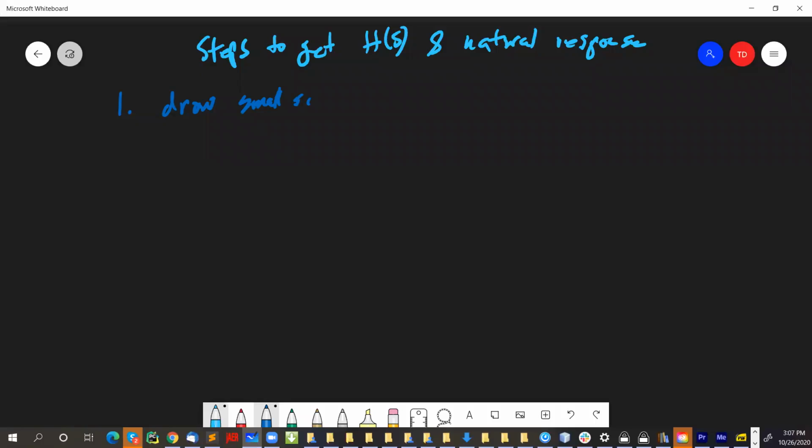The actual transistor circuits are very nonlinear, right? They're exponential and stuff. So draw a small signal equivalent circuit, and so you have something that looks linear with all the voltages and currents. Okay. What's the second step?